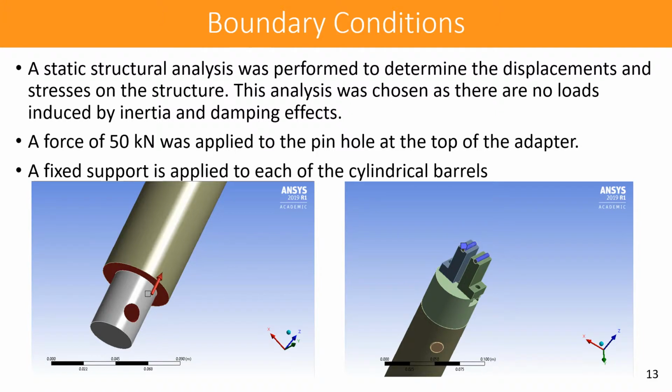Static structural analysis was performed to determine the displacements and stresses on the structure. This analysis was chosen as there are no loads induced by inertia and damping effects. A force of 50 kilonewtons was applied to the pinhole at the top of the adapter, and a fixed support is applied to each of the cylindrical barrels.